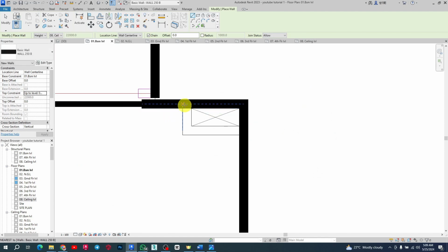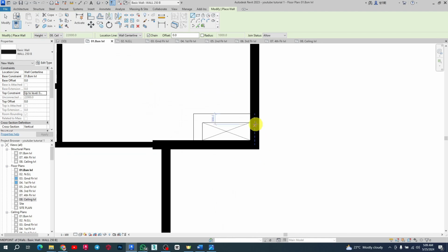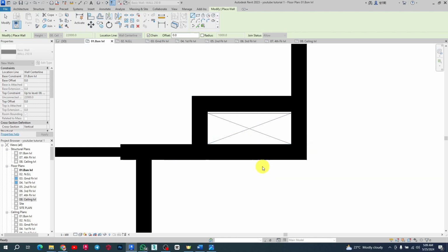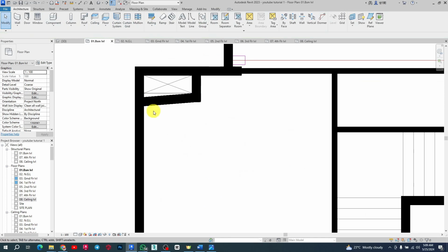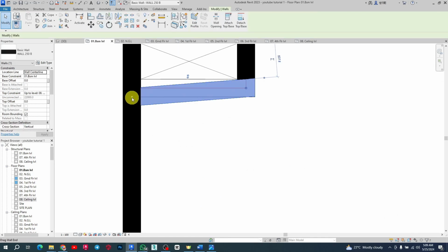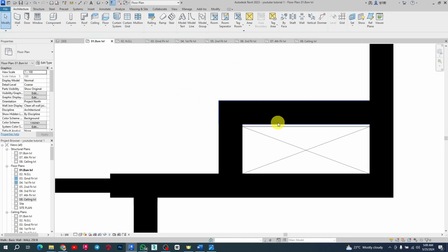So I'm going to come back here. I'll just click, since remember they say Revit is revise and edit, so we're just going to drop the wall there, it doesn't matter. So we're going to come back and fix that. So luckily enough, this one fits well, but this one here is actually not straight, so I want to drag this node here and bring it to the axis. So this is straight right now, but this one here is not actually at the point.